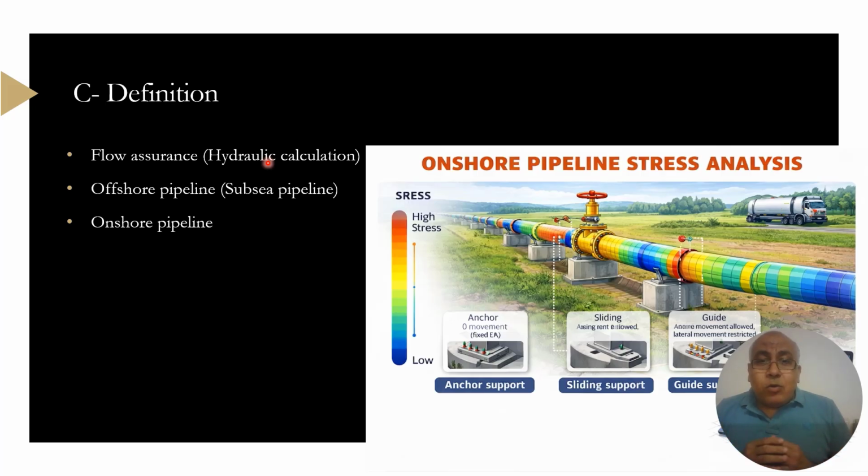Then the thickness of the pipeline: as the pipeline engineer, we discuss together how to define the thickness in case of the onshore pipeline or the offshore pipeline. So this is data. For the pipeline, I also have the topographic survey data, for onshore and offshore, about the right of way, the route, and the stresses affecting it: wind stresses, seismic stresses, according to the load that will be applied on it, in addition to the temperature of the liquid or the temperature outside.